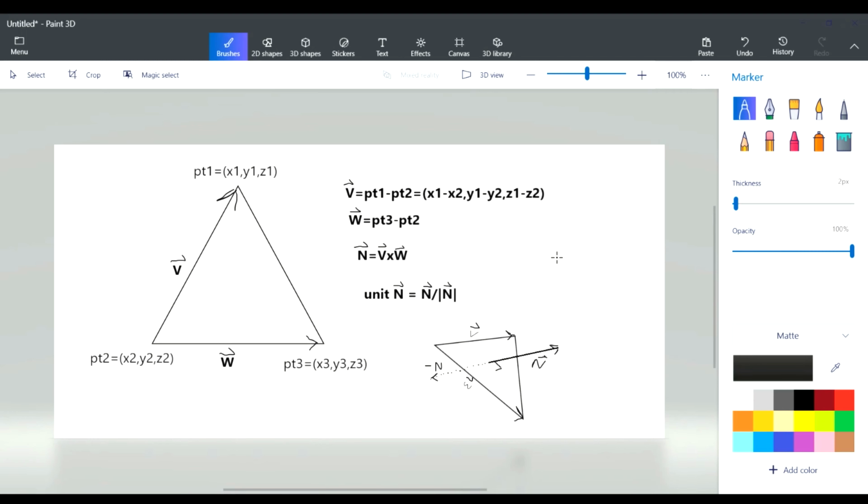One thing I kind of glossed over in the STL format that I showed you: everywhere it said facet normal, I just put 0, 0, 0. And that works most of the time. But what really should go there is a unit normal to the triangle that you're in, that facet. So how would you find that?